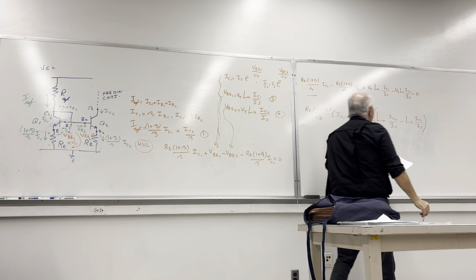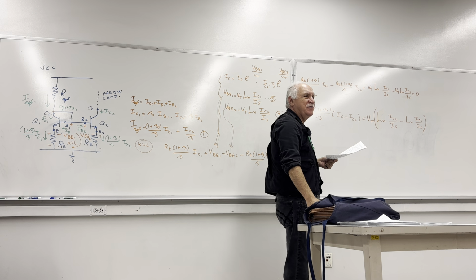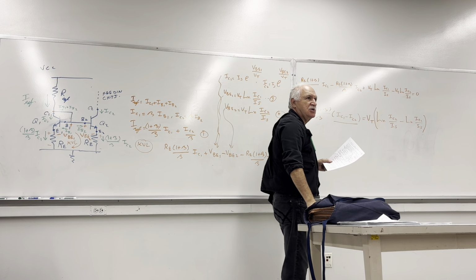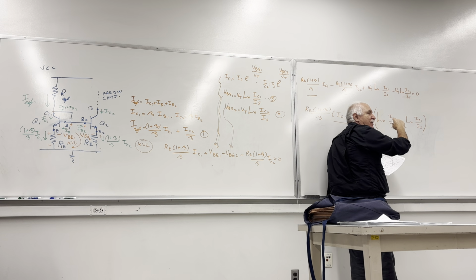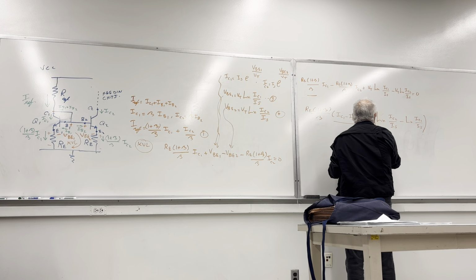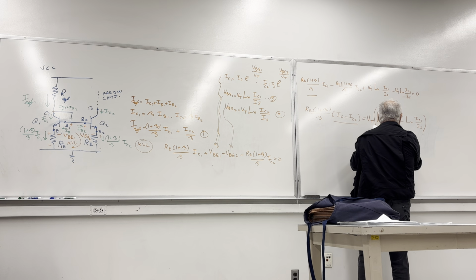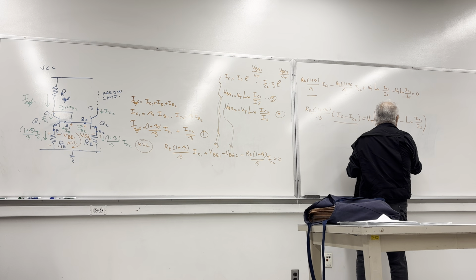All the things closed. Now, the whole thing, the truth will come out of here. You see, we have an IC1 minus IC2 product on this side. This is ln of A minus ln of B. Then it will be ln of A over B, right? The ratio. So this will be equal to VT ln of IC2 over IS divided by IC1 over IS.